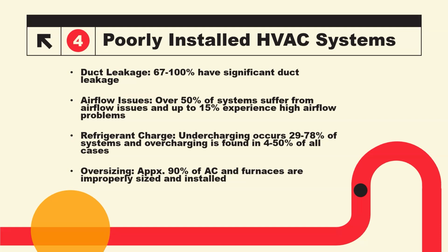It's kind of tough with furnaces in Texas. We're a predominantly cooling climate, which means we need the airflow for cooling more than we need it for furnaces. So we're allowed to oversize furnaces quite a bit to get the airflow needed, since it is a packaged system and it actually runs both conditioning for heating and cooling. So it's kind of tough to say, is that 90% part of the improperly sized equipment? I mean, it may be sized correctly the way it should be, but I'm not sure how energy.gov has done that evaluation for that part of it.